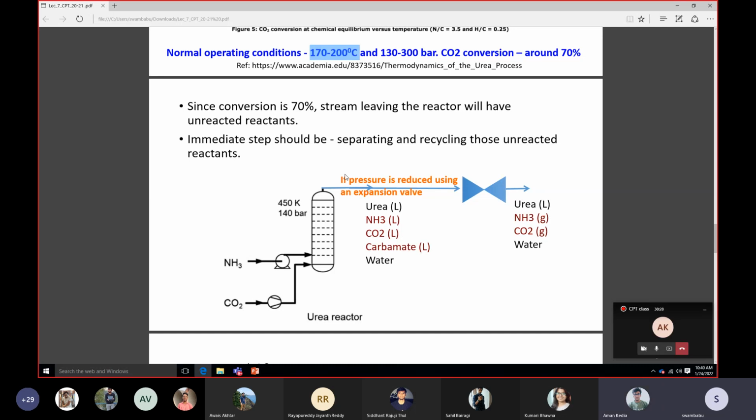Then we can also use slurry reactor. We can use trickle bed reactors. Those are the 4 catalytic reactors. We have only 6 reactors. Always remember, we have only these 6 varieties of reactors which we can use. For non-catalytic reactions, CSTR and PFR, because it is just simple mixing of reactants.